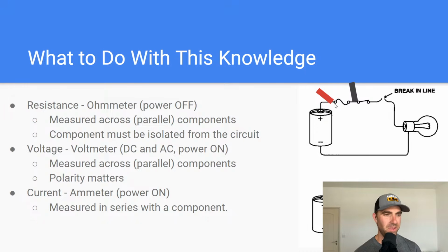So maybe visually you could see that the fuse is blown, but just to demonstrate how you would measure the resistance of the fuse here, you would measure it in parallel. So those are the main notes about using an ohm meter.